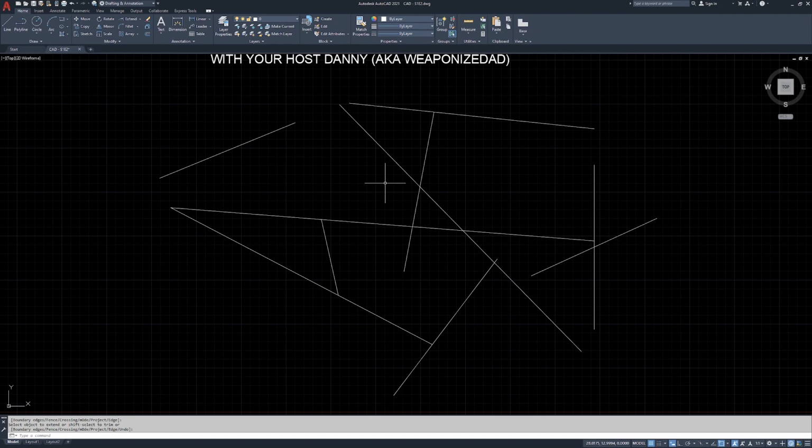So, like I was saying, quick mode is good, standard mode is better in both trim and extend. The implied edge is incredibly important because you're not ever going to be in a situation where all of the lines are going to be touching when you extend them. You actually want that implied edge so you can shoot lines out to a certain point, intersecting at an imaginary point where two lines hit each other.